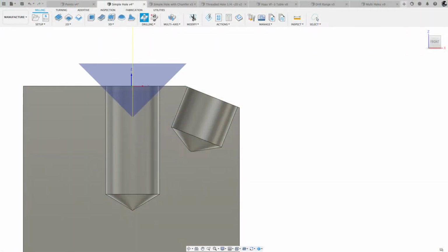a couple full revolutions. And if you think about how a CNC machine works, it's always looking ahead at what the next move or command is. So it's going to come down to the depth and then retract really quickly, and it may not have a moment to pause. That's why I recommend a G82, a counterbore or countersinking cycle, for that reason. So let me switch back over.